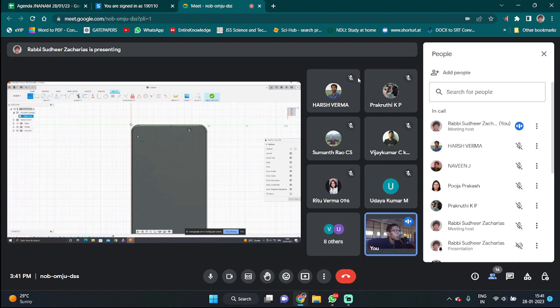We can use this line option. Okay, we had already used rectangle, so now let's introduce this line option. Escape, if you want to just quit using that, you can use the escape option. So using this line option, we can select a start. It has the ability to create lines and arcs. Select a start and end point to define a line segment. Click and drag the endpoint to define an arc. So if you want to draw a line,